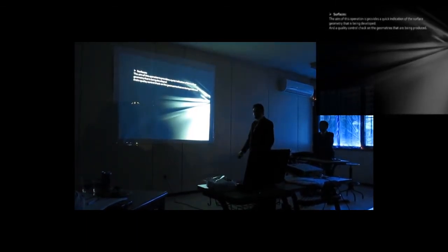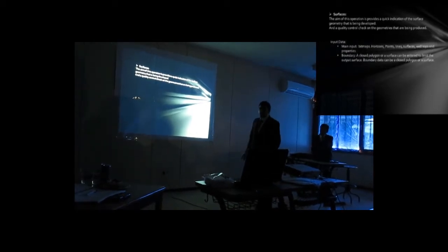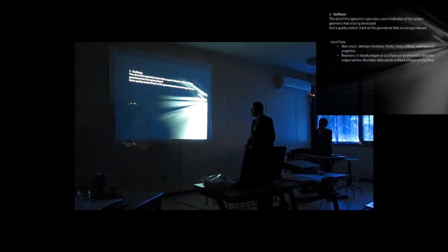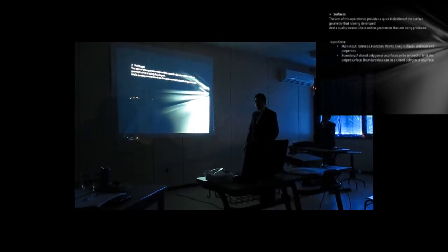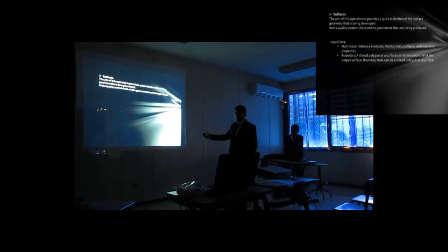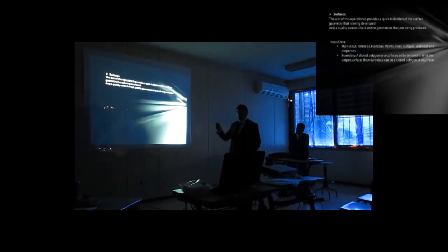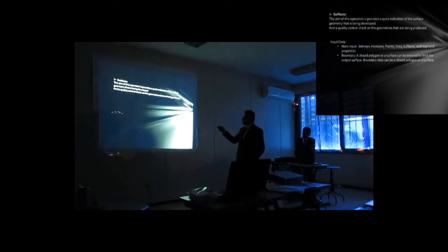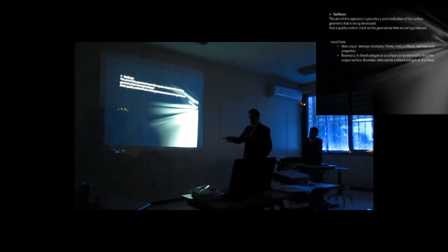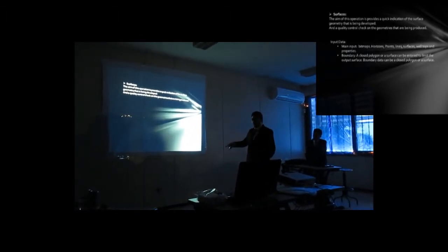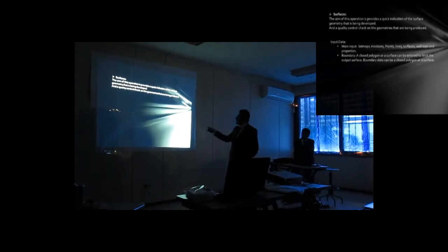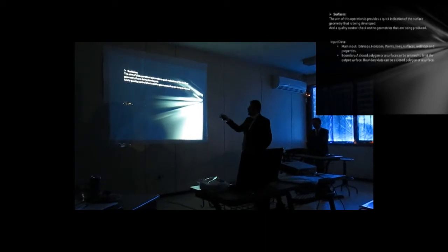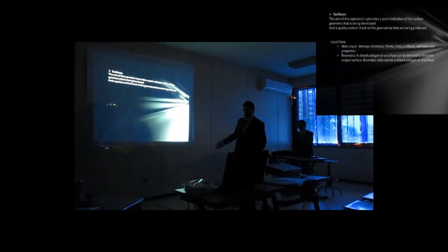Second step, we need to create the surfaces. What surfaces, and what is the aim for creating them? The aim of this operation is to provide a quick indication of a surface geometry that is being developed. As you can see, when we created the horizons in time, they are represented as 3D points, which will take more time to load, and this surface will take each point, or maybe 10 points, and draw a surface for it as an average. So it will help us in defining the 3D grids, and it will be an input for mostly everything in our project.